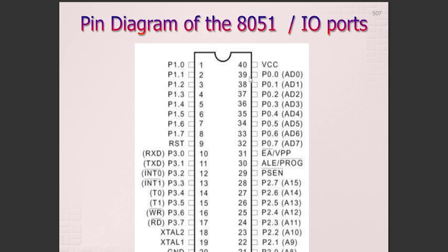To port 1. The port 1, P1, is a true IO port and it does not have any alternate functions as in P0. This port can be configured as general IO only. It has built-in pull-up resistors and is completely compatible with TTL circuits.